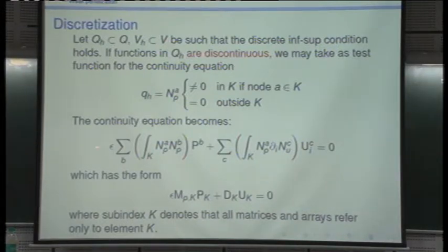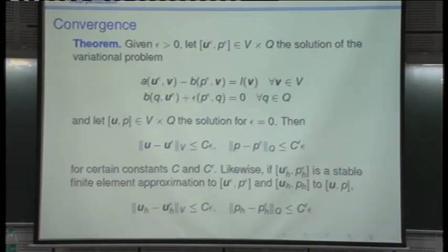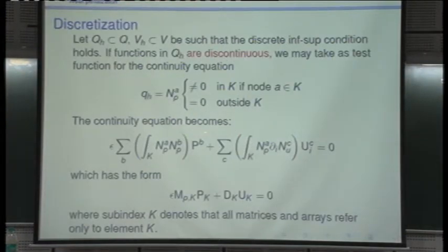So what is the weak form of the continuity equation? Which is the weak form of this equation? The weak form is this one we discretize. We have the sum over all nodes of the pressure shape function times the pressure nodal values. That is the pressure interpolation, and then it is multiplied by the pressure test function,